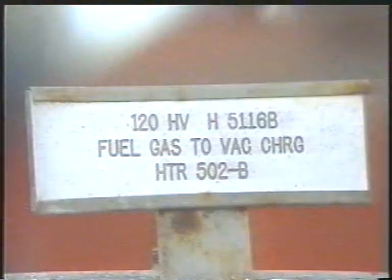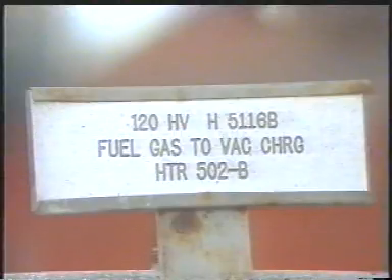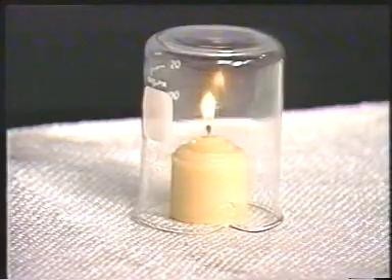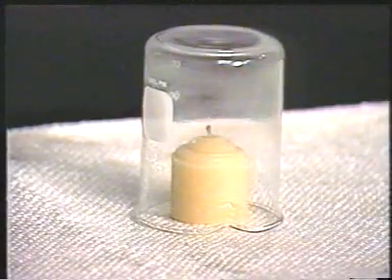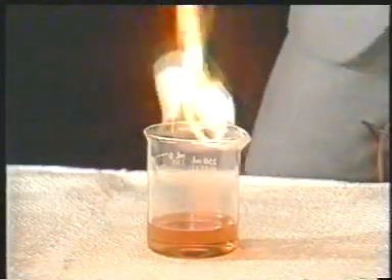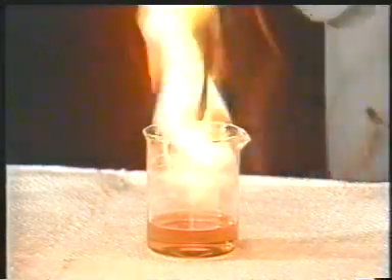The fuel used in a fired heater may be natural gas, fuel oil, or a combination of gas and oil. Natural gas is preferred in many installations because it is cleaner and burns more consistently than oil. Air is needed for combustion because it provides oxygen that reacts with the fuel. The final thing needed for combustion is a source of ignition. The ignition source provides the heat energy that is required to start the combustion reaction.